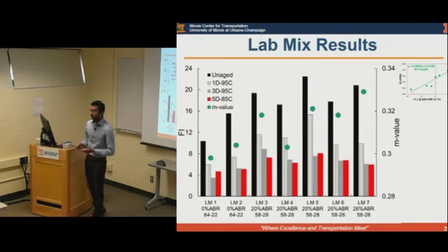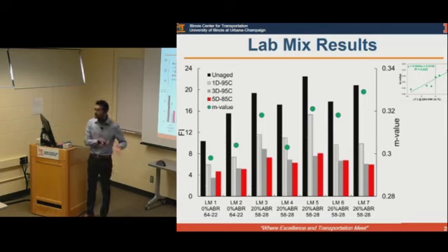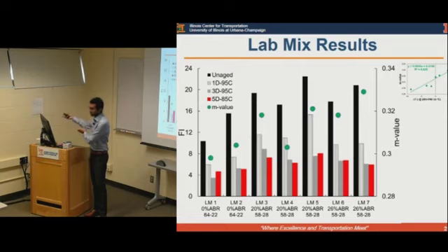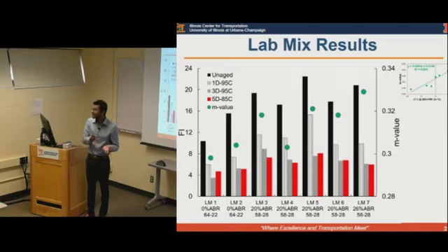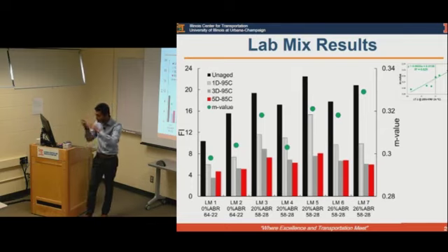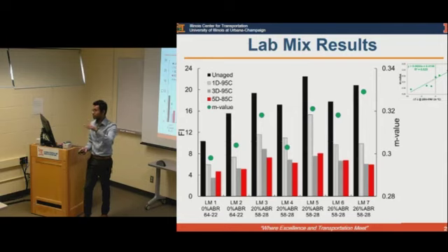Okay, valid question. Thank you for the question, very nice question. The thing is, we need to develop the fundamental science behind this mechanism. We can do another test, we can correlate, and we can check the performance. But there is an underlying fundamental mechanics behind this aging, and that's what we are trying to validate. Because right now, whether 5-day aging at 85C is real field aging or not, and actual pavement performance is not just the surface mixture; it is the performance of the entire structure. With these tests, we can talk more about just the mixture which you're placing on the field, not the entire structure.